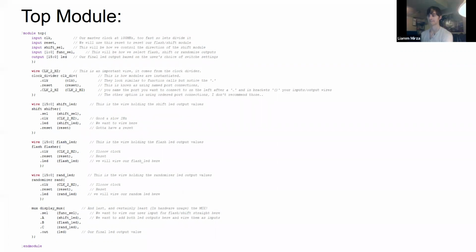I think you can instantiate it without the names, but Vivado will complain. You can? But then you wouldn't be able to do it more than once. That's the problem. You can do it once, but you won't be able to get away with it more than once, because then it'll assume you're trying to call the same module twice. I think that's a case where it'd give a lot of errors, but it'll still generate some hardware. And if you have more than one module, it'll silently delete the other one, if it does actually generate a bit stream.